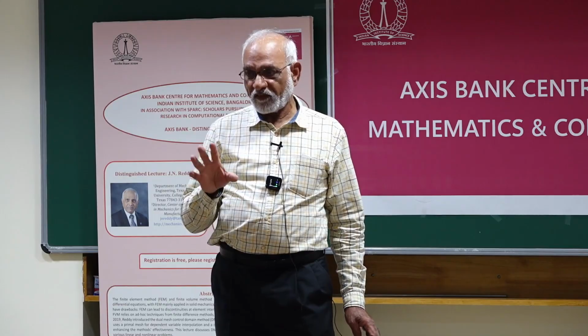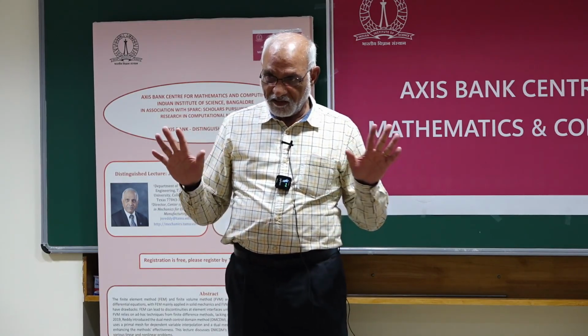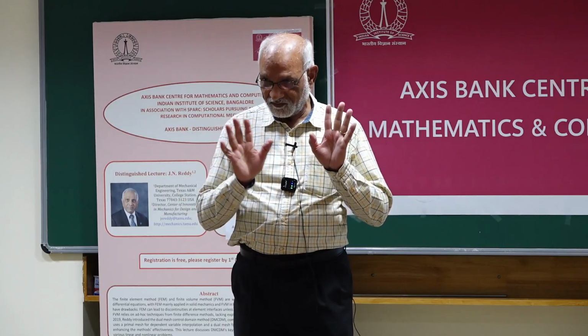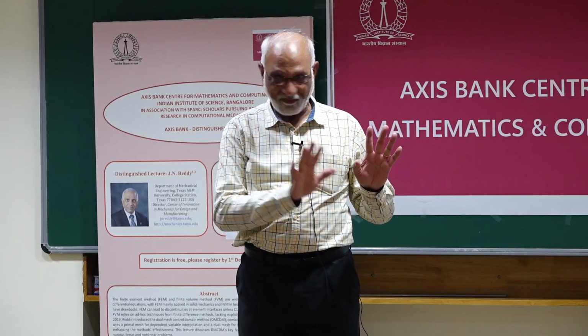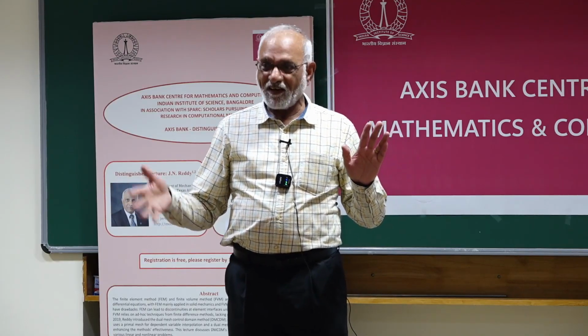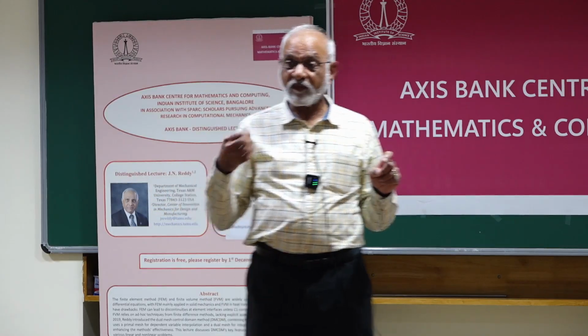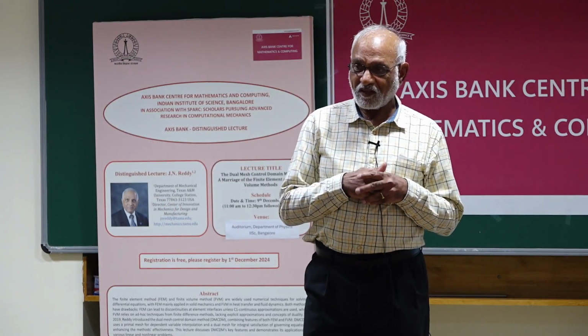Okay, so the physics requires you to either use the same description, which is say Eulerian description, for even solid mechanics, which is a bit complicated, or you must bring rate dependent constitutive equations so that your field variables are velocities, not displacements.